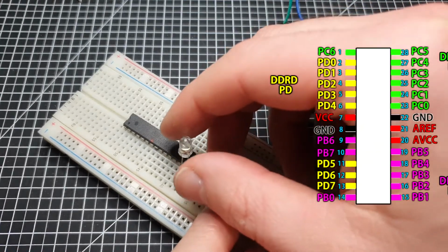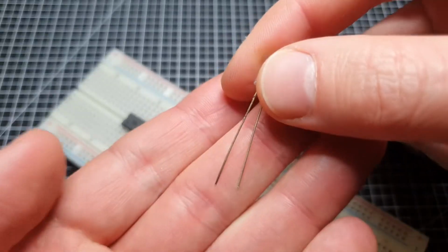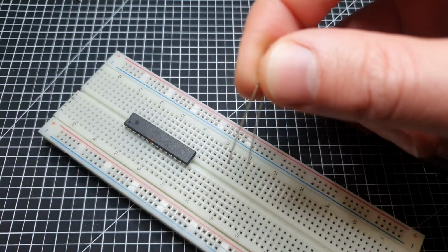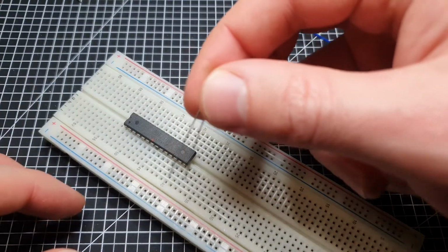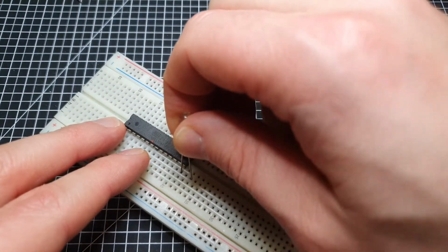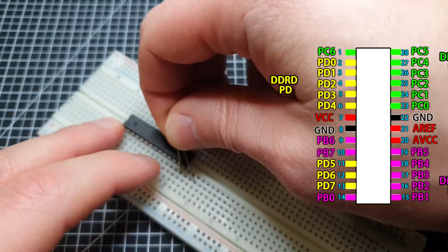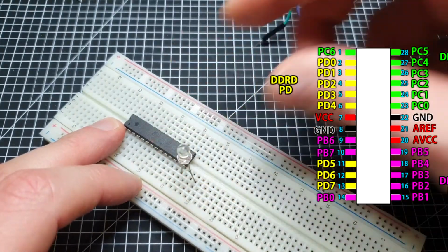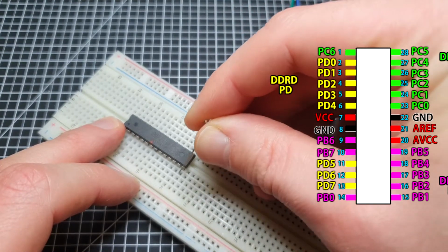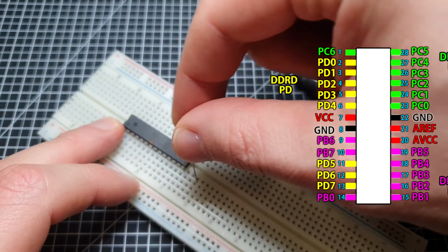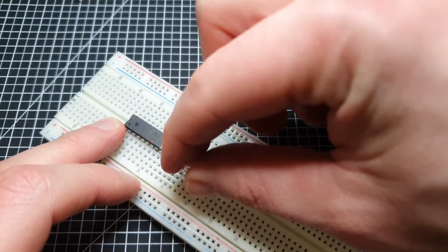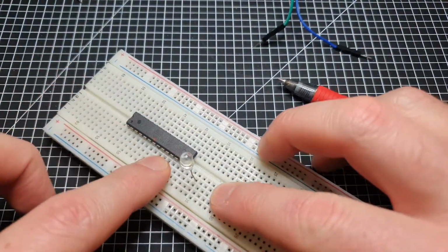How do I know which is the positive? It's the longer one. The longer one that you could cut up and make a cross with, a plus. That's the positive one, the longer end of the LED. So you just stick that into PB0. And then the negative end, we're just going to put it off to the side. It doesn't matter where. You could put it over here if you wanted. It really doesn't matter. So just put it off to the side there. Make sure it's in there good.